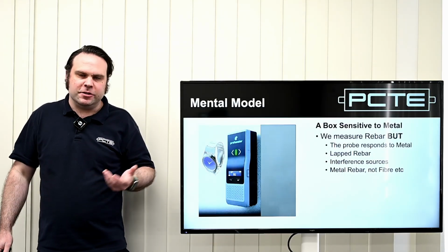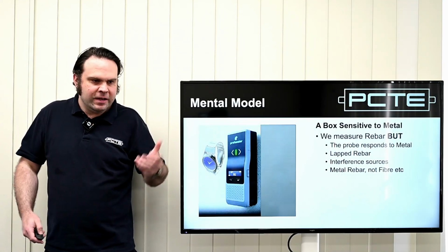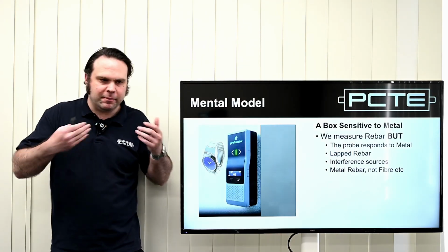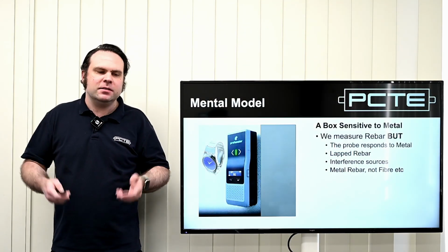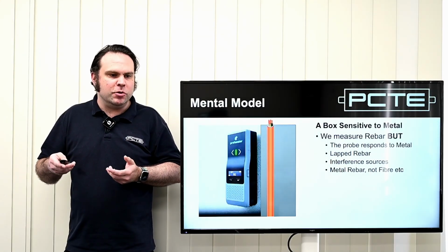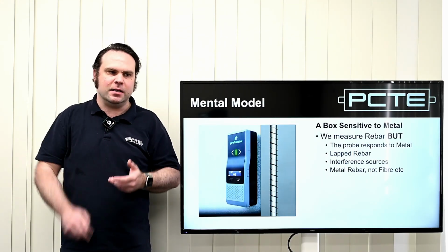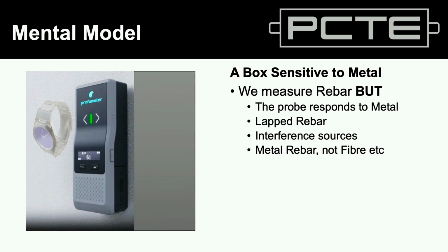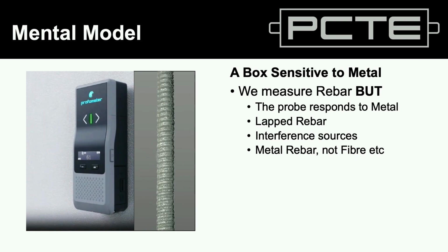We also want to watch out for interference. Don't wear watches, sort of keep steel cap boots if they're metal away from the cover meter, and work to find that ideal circumstances, which is that single bar isolated under the cover meter. And that's the process I'll teach later. The other thing is, because it is only sensitive to metal, it's sensitive to metal rebar. We're not going to get any signal response from carbon fibre or fiberglass reinforcing.